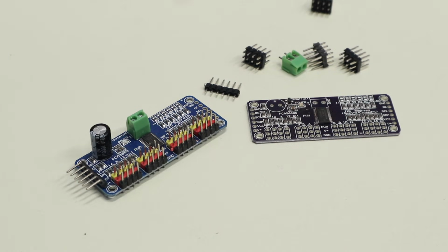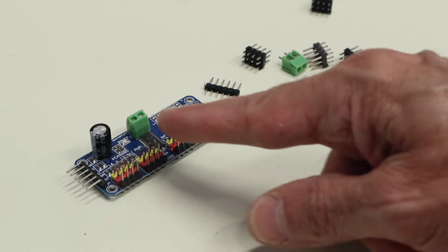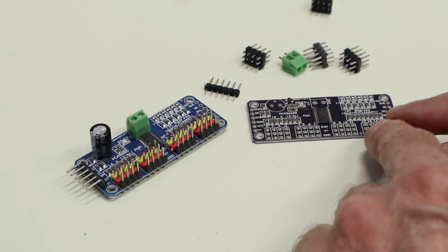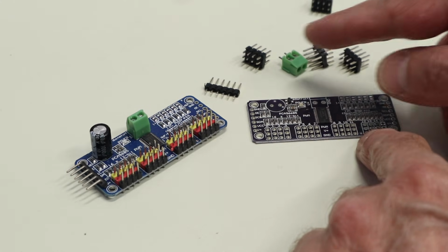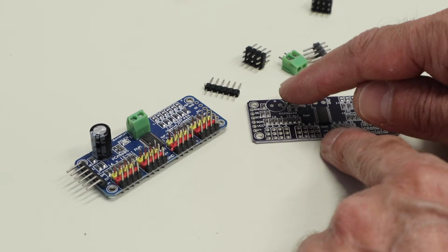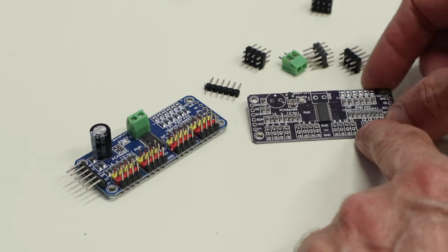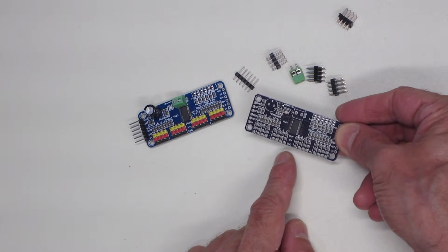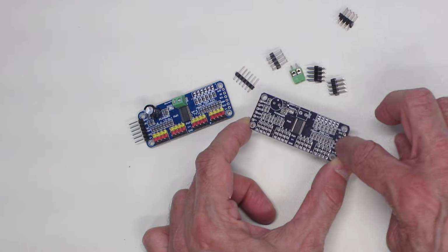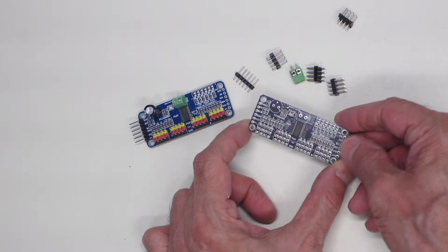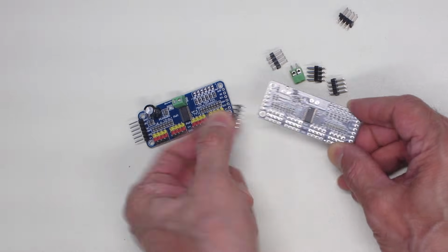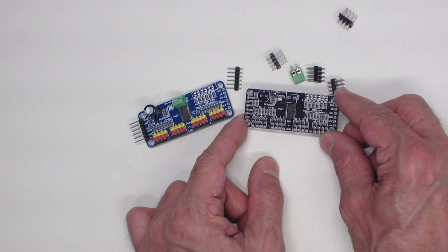Now here are a couple of PCA9685 modules. I've got one here that is completely assembled and one that comes unassembled, so to speak, because all of the headers and the terminal for the power are not connected to it. You'll also see there's a large capacitor over here that isn't on this board. This board can actually have some advantages. If you want to mount this, for example, onto a printed circuit board, you could take the edge connectors, and these edge connectors are actually duplicated on both sides, so you can daisy chain these modules, and you could put the pins underneath the board if you wanted to, like that, if you wanted to solder it down onto, let's say, a printed circuit board.